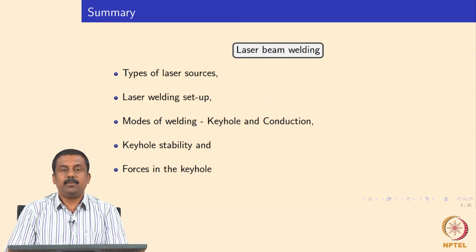The conventional process uses a constant current. For example, the amplitude of current is constant throughout the welding process. There are some disadvantages in terms of heat input, the amount of heat you put into the workpiece, as well as the transfer characteristic. So what do we mean by transfer characteristic? It is how you transfer the molten droplets from the electrode to the workpiece.